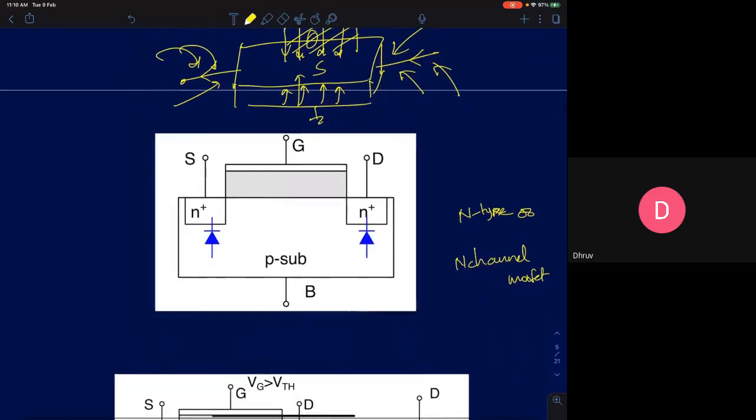So first, the structure of a MOSFET. A MOSFET has a semiconductor. So this is the semiconductor. The whole idea is to have a semiconductor and create surface carriers. And we have a metal, which is where we will be applying our positive or negative voltage. So this is a MOSFET. Typically we apply a positive voltage. And then in between we have the oxide.